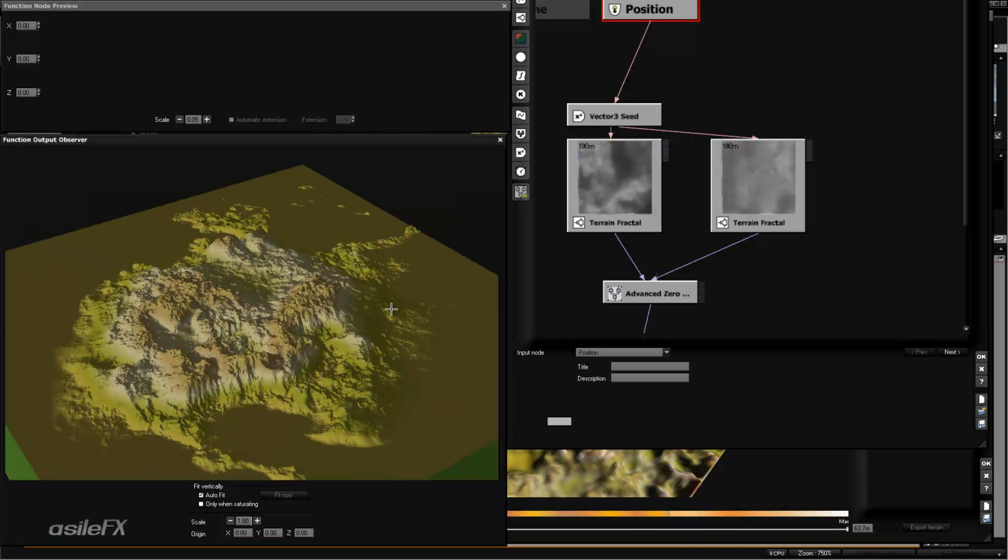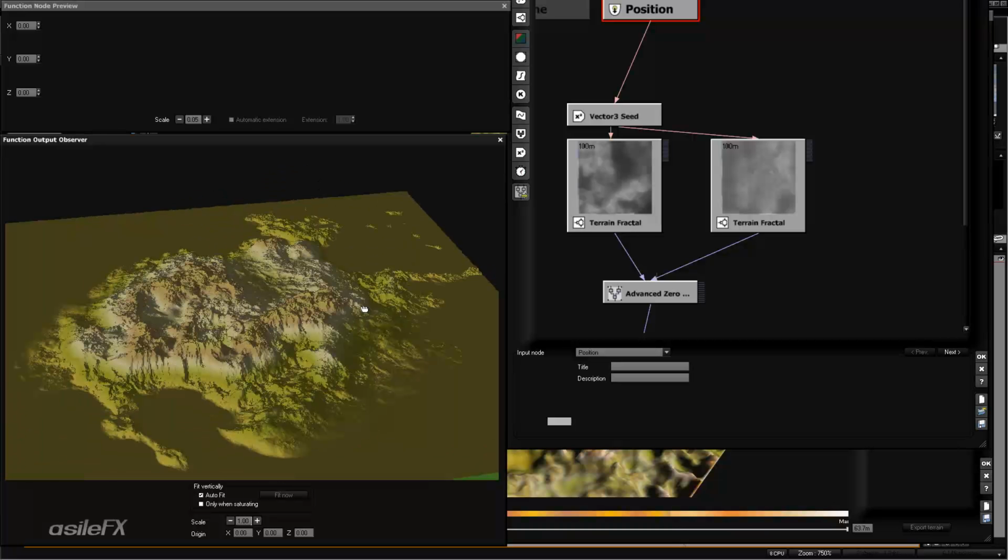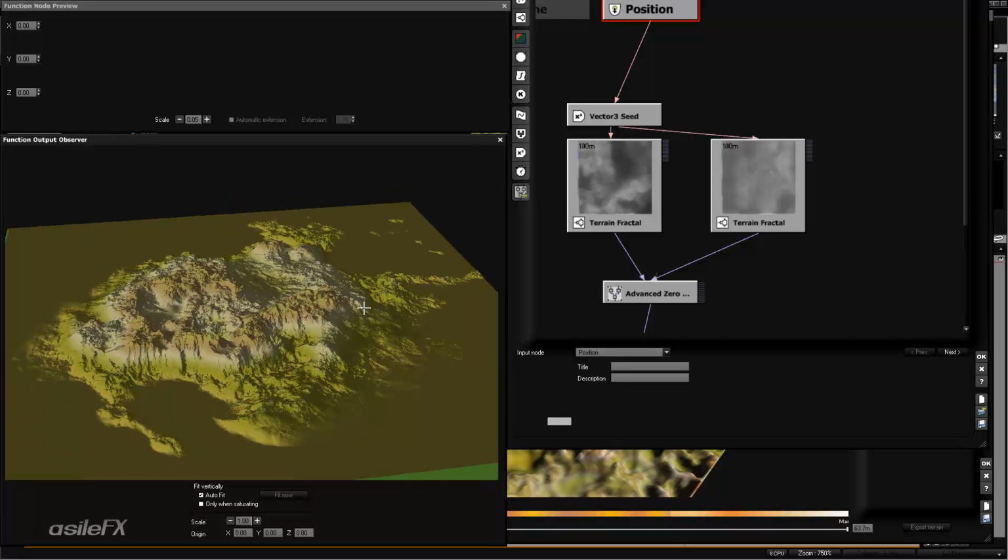It does render faster. I did a lot of tests in View 8 when I discovered it, and I did training for Terrain Workshop, and within the booklet that comes with it, it's called the 0Z technique, which describes all of that. So it is going to render a bit quicker, and it also cuts down on some of the roughness and distortion around the edges of terrains, and does change the roughness output. So it's still good to start with. Changing it over to the position options is not really going to modify too much.